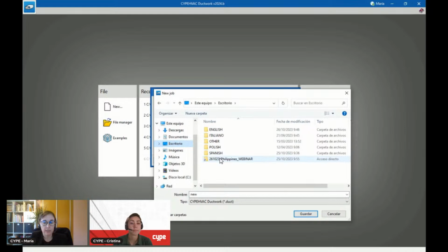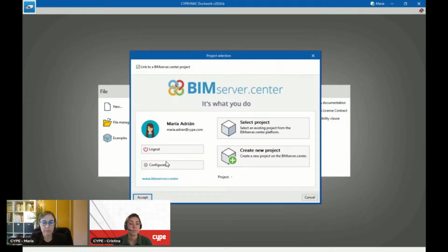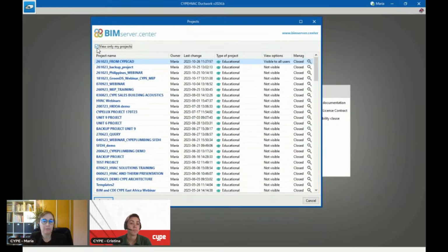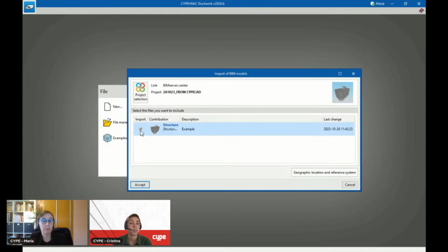I'm going to save it in the folder for today's webinar, and I'm going to call it ducts. Let's save it, accept, and now I'm going to link this file to the project. At this point, I select project, and I say that I only want to see my projects, so it filters a little bit. Which project do I want to use? The one from SideCAD. Let's double click it. By doing this, now I'm able to import the structure. Let's accept.